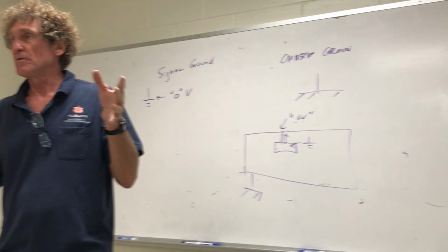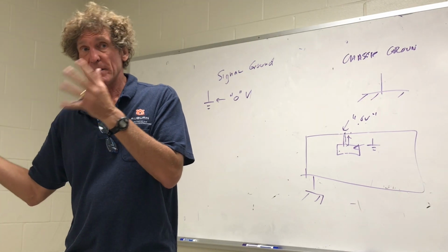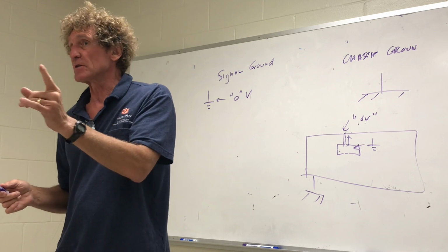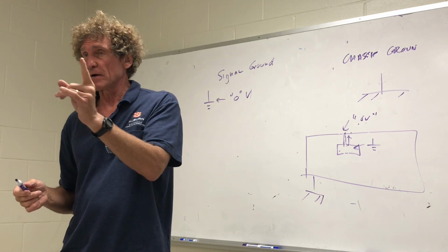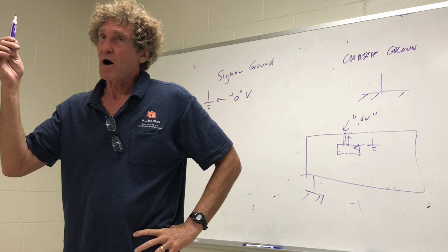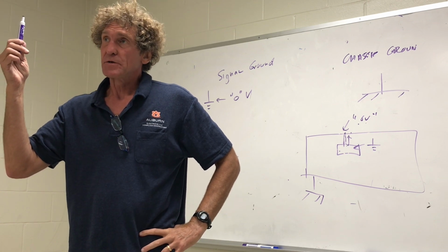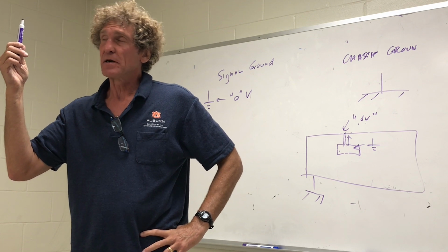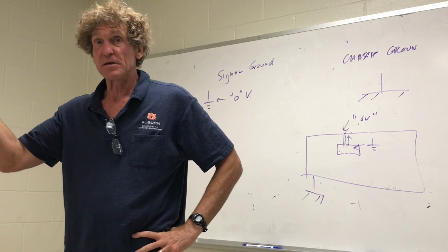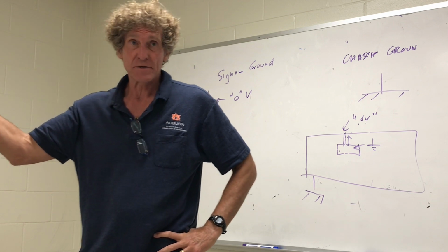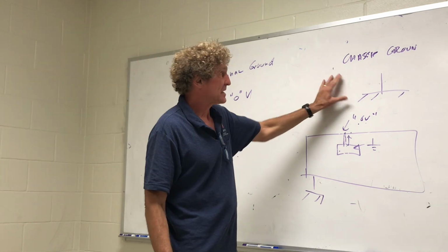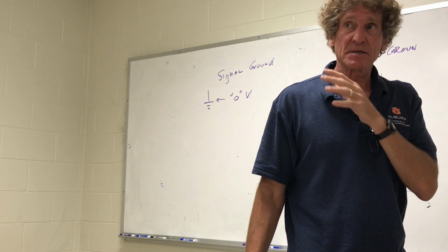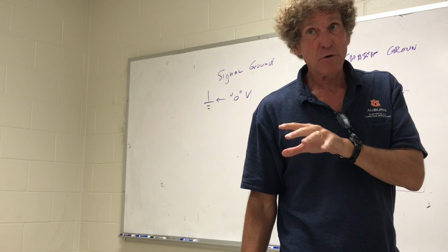You take that and you do fast Fourier transforms on that with a spectral analyzer, and you'll see the frequencies. 60 hertz is the dominant one, a very low frequency you have to get rid of. Then as you go up in frequency, if you have oscillators, you will see the fundamental for the clock frequency. If you've got 2 gigahertz clocks on there, you'll see that, but it's usually the higher frequency components, the rise times of that, that you'll really see. That's the chassis ground.